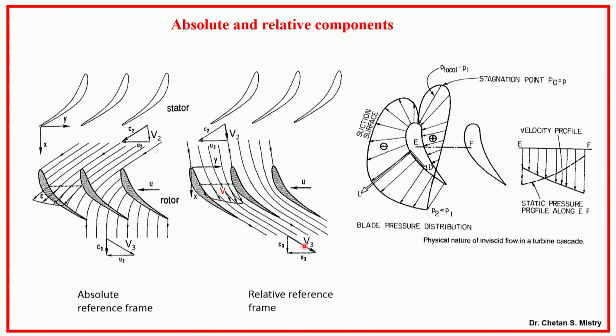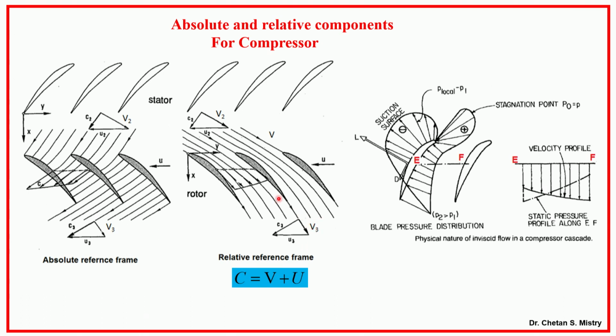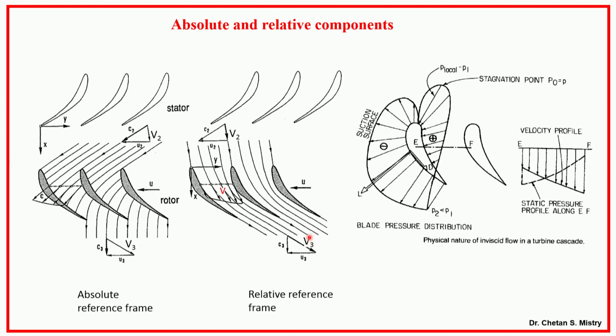If we move back, this is the comparison for your compressor as well as turbine. So, for the turbine, we will be having a lower absolute velocity with which my flow will be coming out. Okay. Now, here if you look carefully at what is happening on the upper region, like this area, and if I move towards the downward side or trailing edge side, my area is decreasing.